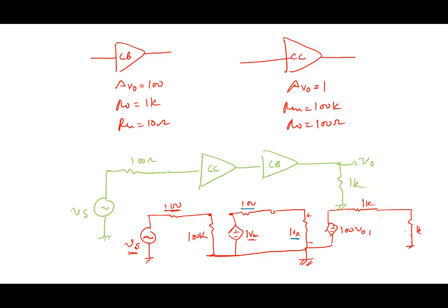Okay. So the common base has such a low input resistance that unless the common collector's output resistance matches this, you have to build a common collector amplifier such that it is also 10 ohms maybe, right? 10 ohms, then maybe you could build a higher gain amplifier here.